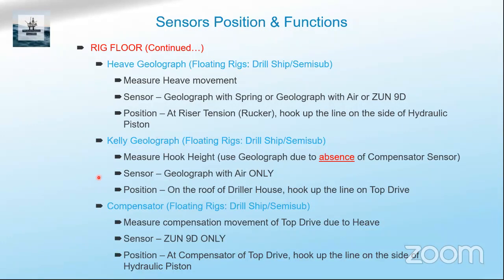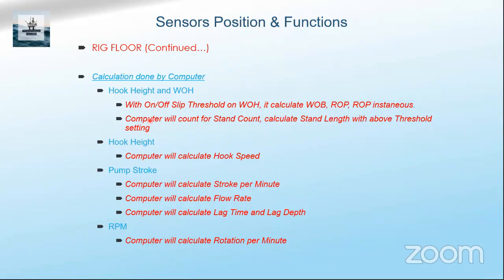This is some of the offshore. We will not go through it all. An important thing is, we are not talking only about the sensors. As I told you, some parameters are calculated ones. For example, weight on bit, there is no sensor for weight on bit. It is a calculated one. Rate of penetration is also a calculated one.